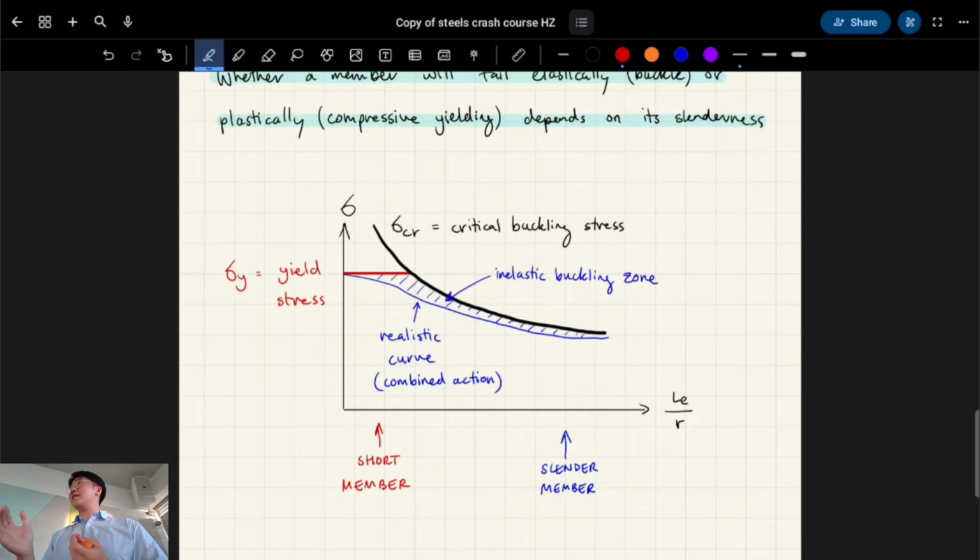But buckling effects only really kick in when you have a slender member. If you have a stubby member, you essentially don't have to consider the effects of buckling. But for slender members, the material strength, like what we calculated in tension, for example, but the compression version, gets significantly weakened by buckling effects. Make sense?